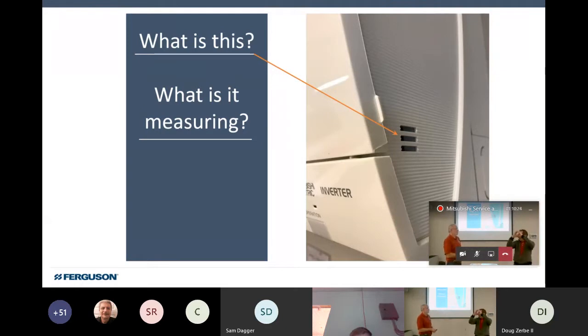Because you think about it, when you look at the size of that hole in the wall, a 3-inch round hole with your stuff coming through, or a small few slots, under that negative pressure and the vortex of air that's being circulated in there constantly, it's going to pull from the path of least resistance, which is going to be the bigger hole, and then we're not sensing that temperature.